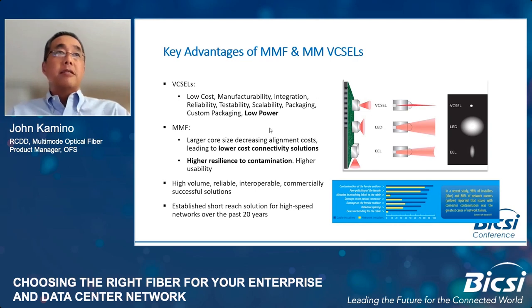Some of the key advantages of multimode fiber VCSEL-based systems are driven by the source that's used, a vertical cavity surface emitting laser, or VCSEL. VCSELs are very low in cost, and they're very low power consumers. So that means that from an operational perspective, you have an advantage. And if you look at data centers today, where you can have tens of thousands or in hyperscales, 100,000 servers, you realize how important it is to have lower power consumption.